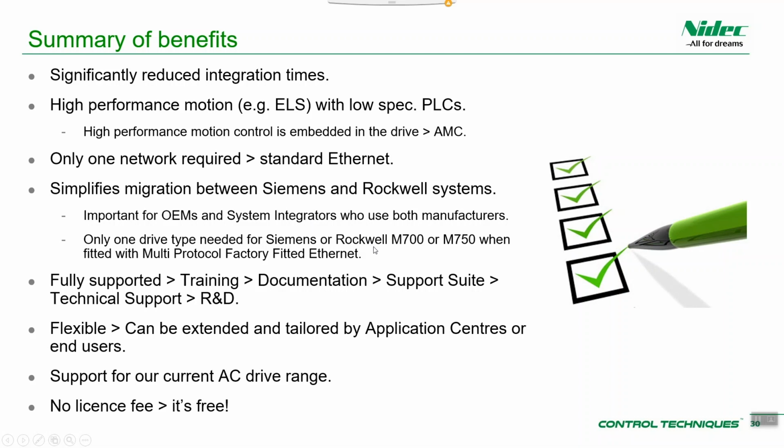One thing to note is that if you do have a system and you're working with Siemens and Rockwell, then the M700 or M750 Digitax HD drive, when fitted with the multi-protocol factory-fitted Ethernet module, is able to work over Profinet Ethernet communications, and it's able to work with EtherNet/IP communications. So no matter which PLC you're working with, really you only need one drive there to be able to work with either of those communication protocols, which is quite helpful.